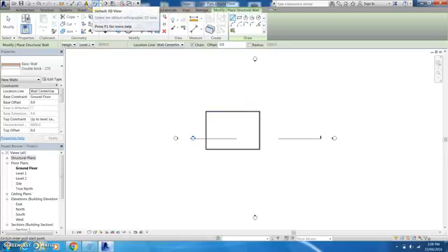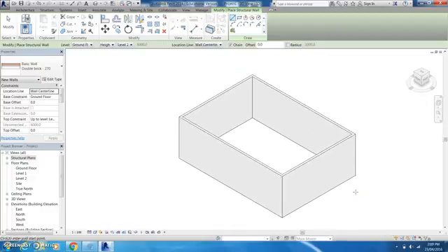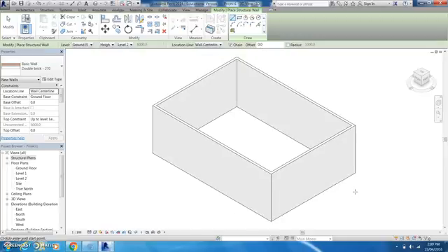I've got my little house button up here. Now my little house button is very important because that is going to show me my drawing in 3D so far. And there it is. So I've basically drawn 4 double brick walls, and you can see that by using my cursor I can highlight certain parts. I can also move that around, pretty similar to Inventor, to have a look at it. Also, guys, the same rules apply with your mouse in terms of scrolling in and out using the center and highlighting,